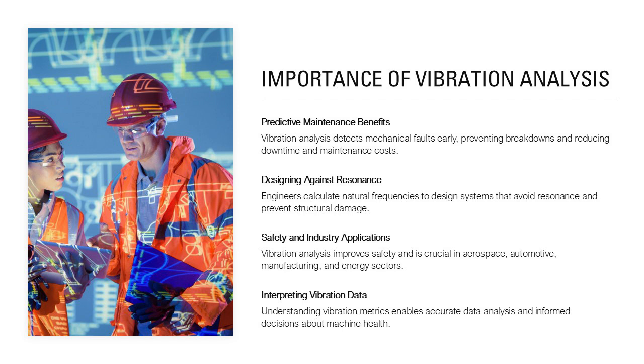Vibration analysis also plays a role in product design, ensuring that components can withstand operational stresses without resonating at harmful frequencies. Resonance occurs when the natural frequency of a system matches the frequency of an external force, leading to large amplitude oscillations that can cause structural damage. Therefore, engineers must calculate natural frequencies and design systems to avoid resonance.